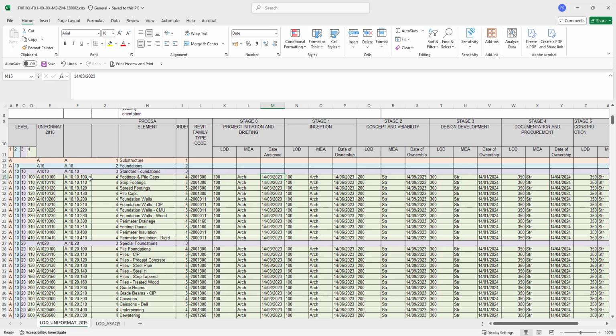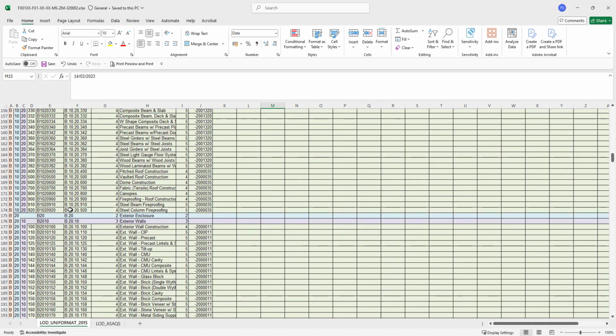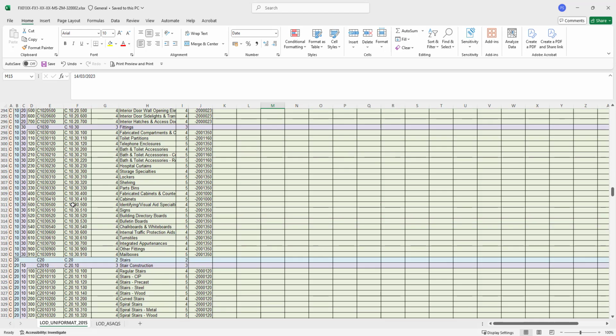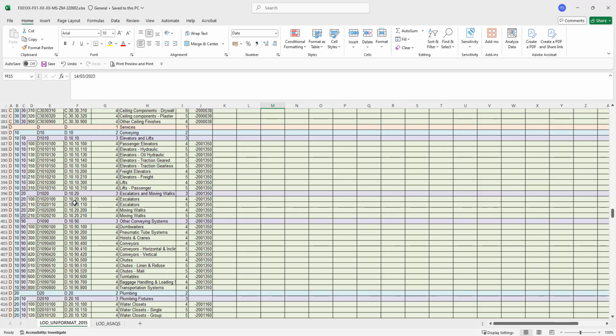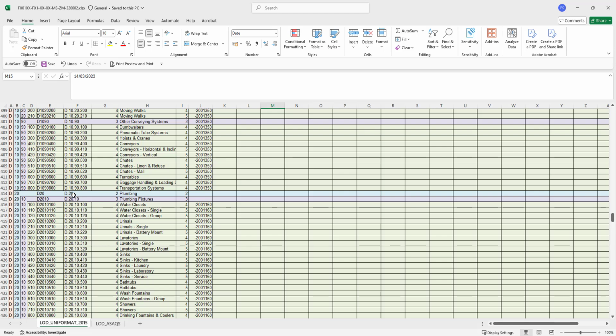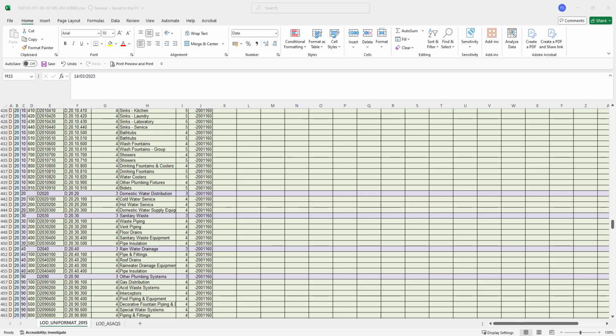And so if we were modeling, say for argument's sake, a pressure pipe network in Civil 3D, and we want to impart the relevant codes onto pipes and pipe fittings and such, then we would have to know where to find that in the standards, which would be pipes. So there we can see we've got conveyancing, we've got plumbing. Under plumbing we could probably look at domestic water distribution.